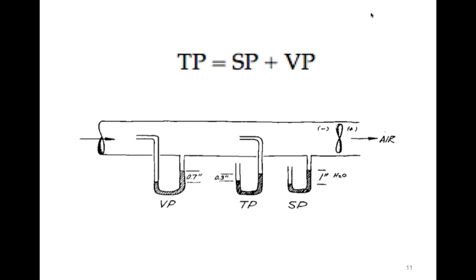So you can imagine that's going to start sucking. It's going to suck air through the duct, but it's also going to pull with equal vigor air up through that tube. Since there's water in that tube, it's going to draw that water up. Now, if there were enough suction there, it would suck the water right out of the tube. But most duct systems and fans don't really generate that big a difference in pressure.